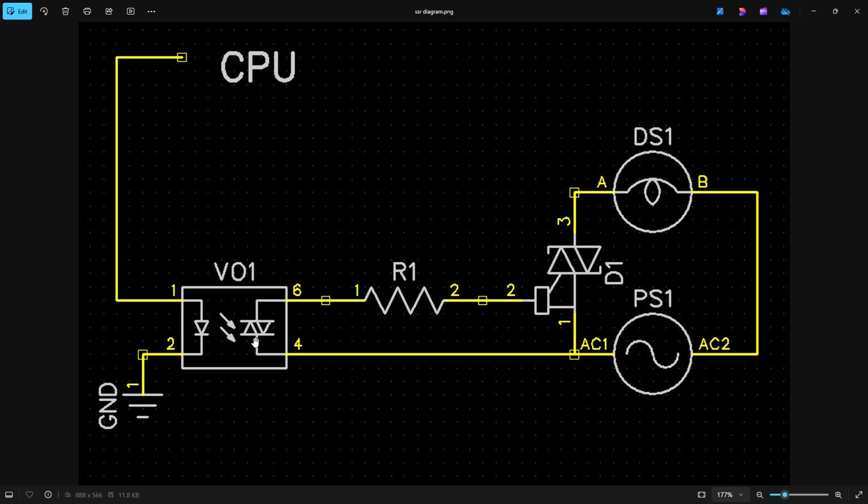Turn off this LED. This stops conducting. Comes over, no voltage goes to the Triac, so we have to wait for the 0 cross, but when the 0 cross hits, this will automatically then turn off. So I've just described a solid state relay into a light dimmer. Okay, so now what we're going to do is we're going to go look at some data sheets, and then we'll jump over and we'll look at some real world operation of these.